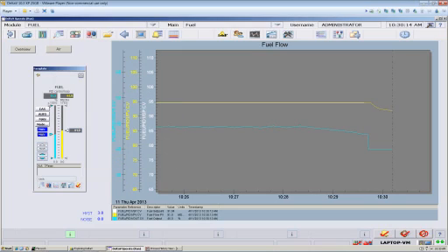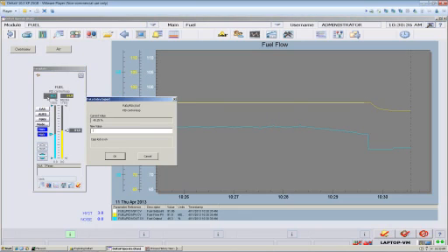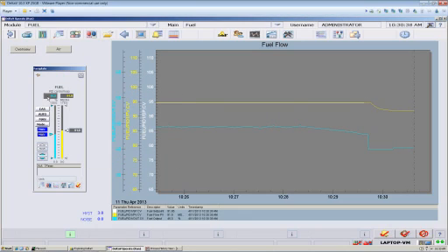And believe it or not, on a well-designed, high-quality valve with a good positioner that's in good mechanical shape, I expect a 0.25% precision from my valves. If I command the valve to move by 0.25%, I expect to see a change in flow. And in my example here, I didn't. We'll go back to 45, and there's no change.